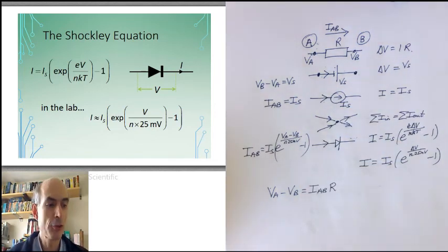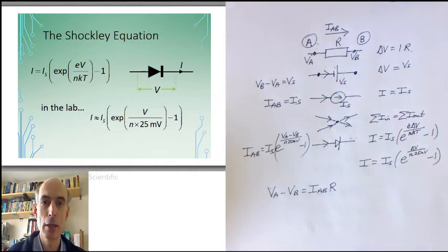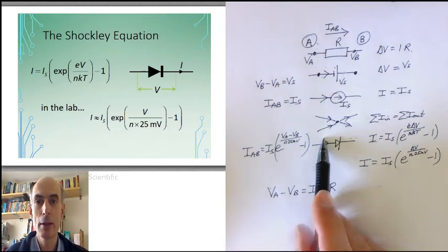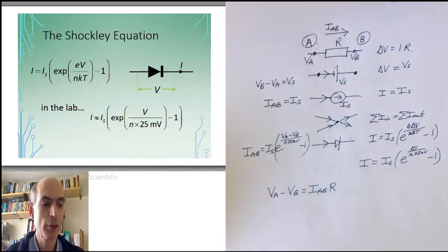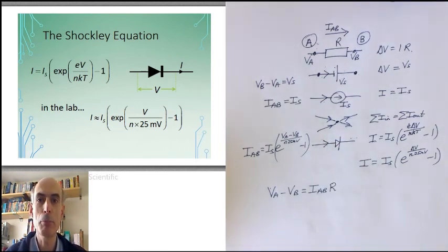When you do the analysis, some of these current values may turn out to be negative, which would tell you that in fact the current is flowing the other way. But while you're doing the analysis, define which direction you are treating as a positive current and stick to it. It'll get easier with some practice. Okay, in the next short video, we'll look in a bit more detail about this algorithm, the nodal analysis algorithm.